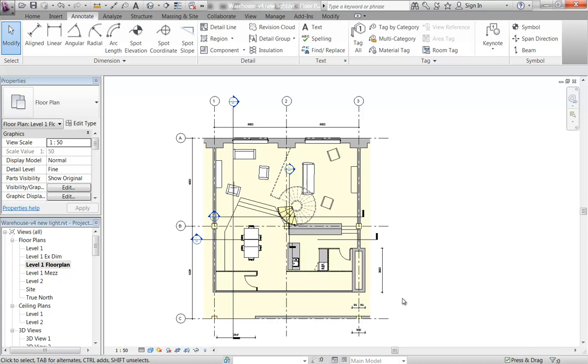Now look, it doesn't need to be fully dimensioned, but the overall dimensions. But does that include furniture and things? No, no, never dimension furniture. We do it for institutions. It depends what it is. So built-in furniture, you can dimension the overalls, and then your main walls, definitely room sizes.